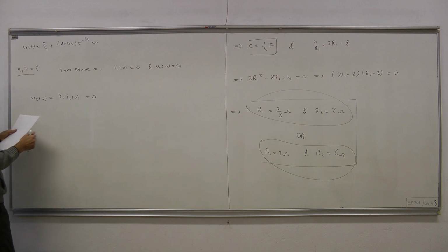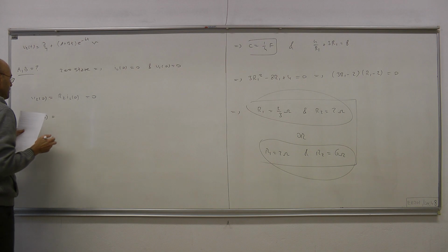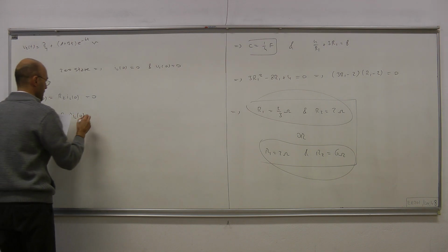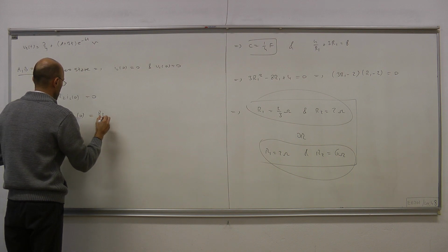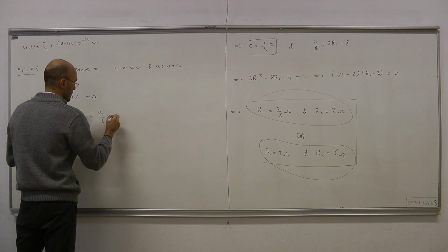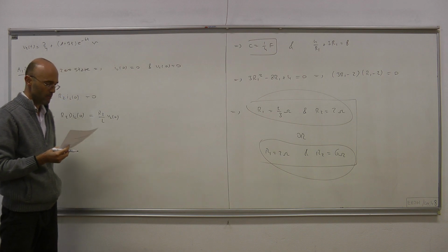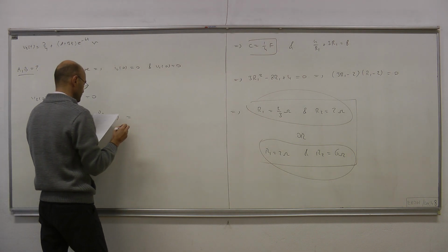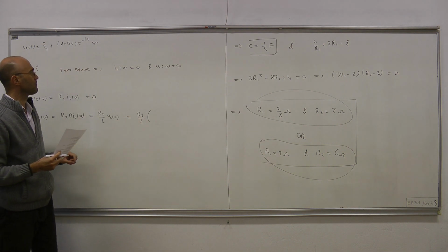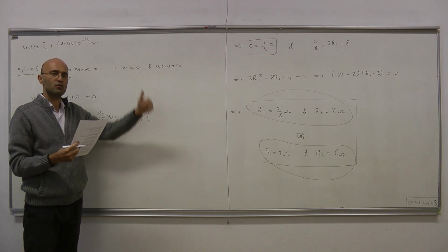And how about dV2(0)? So this is R2 dIL(0), and that's R2 over L times VL(0). Okay, because dIL is VL over L, and then we can write VL as what? VC minus V2, and V2 is R2 times IL.